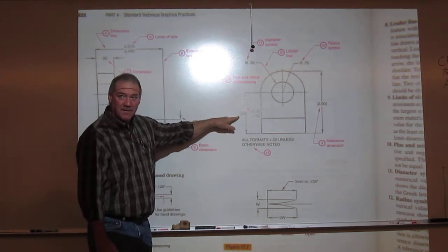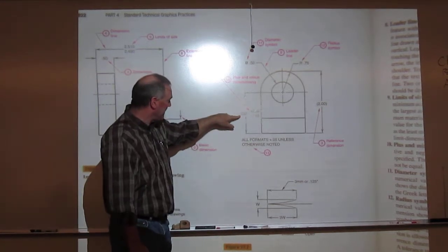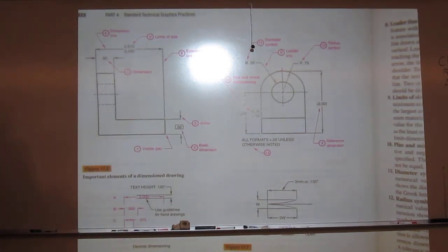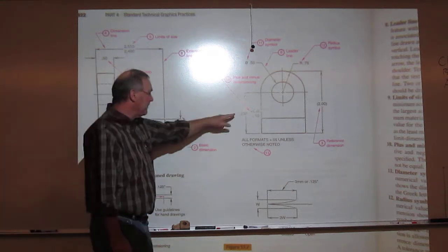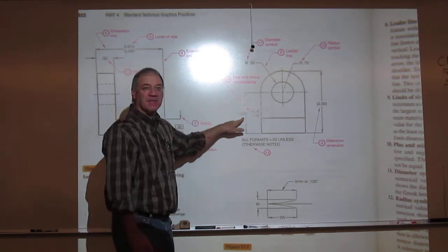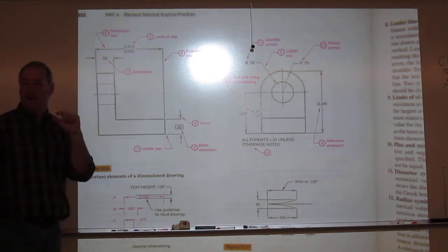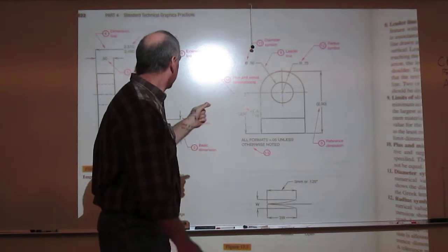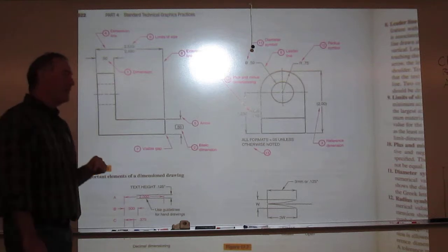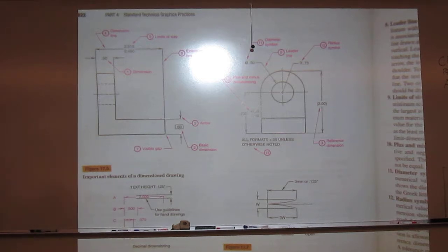This is the same thing, plus and minus dimensions, but it's listed different. It's given a basic size here, and then a deviation in the positive and negative direction. Now this can be kind of weird. You want to pay attention to these on the plus minus, because what we're telling them here, I think that says 1.25. Does it? Okay. So we're telling them that's the size we want it. We want it 1.25 inches. Okay. We want it that size. But we know you can't build it to that size, so we're going to allow you this fluctuation.